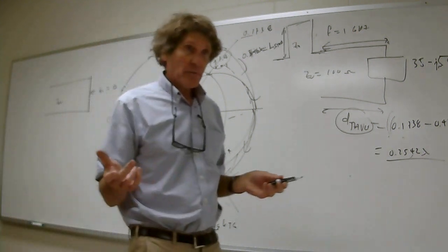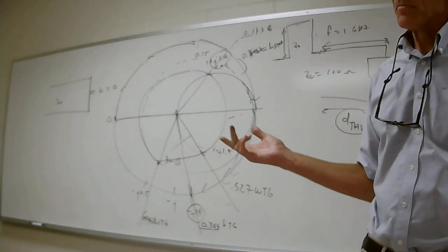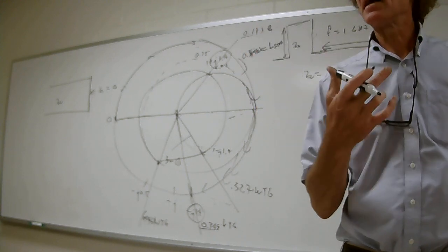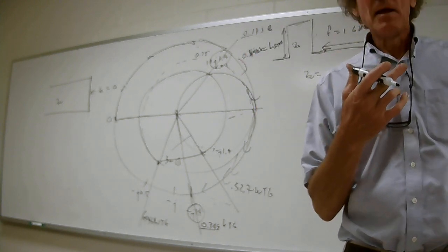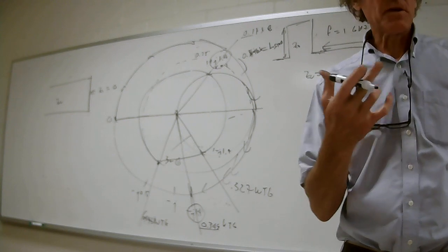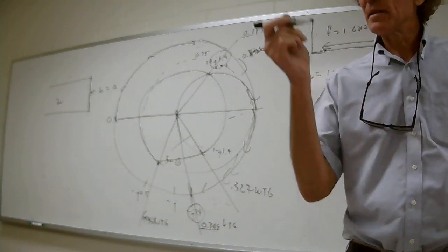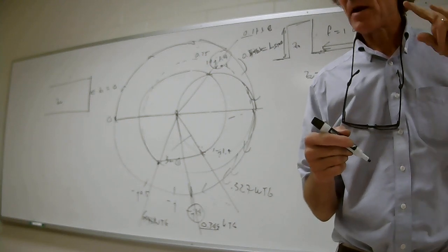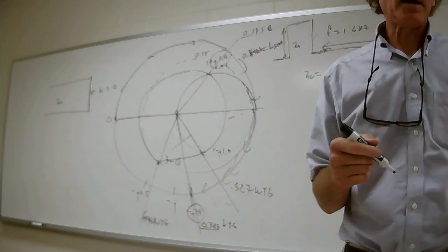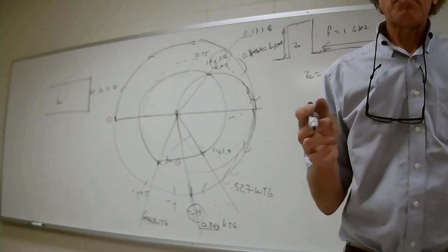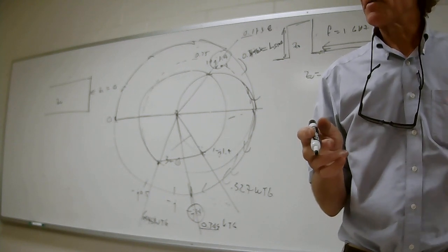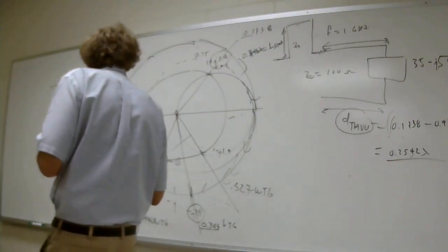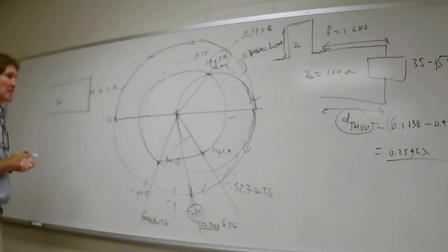inductors in parallel. Do you all remember that? Why don't you? Because if you're using any DC, like feeding a bipolar transistor, bipolars always have a DC offset. If you use that as a feed line, then you can't have DC offset. It'll short it out. So for good design practices, you put inductors in series, capacitors in parallel, if at all possible. An inductor in parallel causes nothing but trouble, usually. Just telling you.